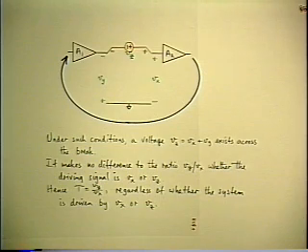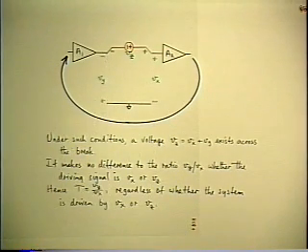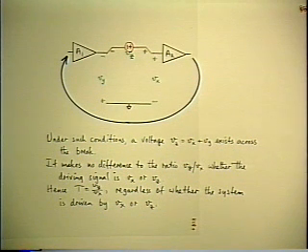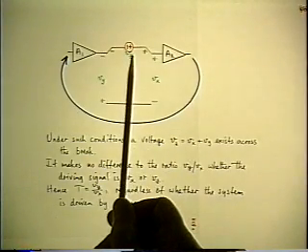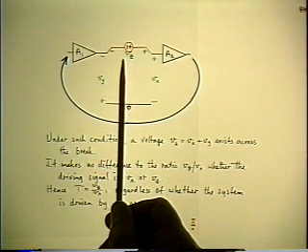1. And I take the voltmeter and hang it across Vy. What does it read? 10. What's the loop gain? 10. Same as before. So you get the same answer. So what's the difference between the two methods? The difference is the loop is not broken this time.